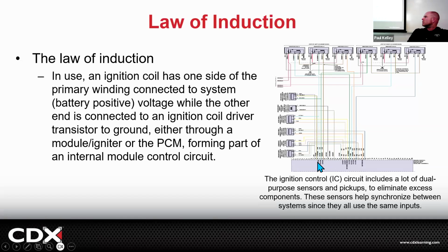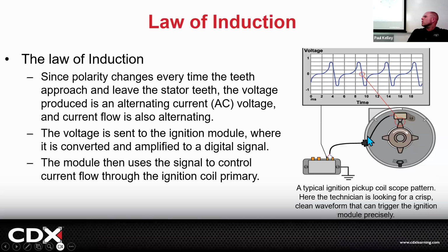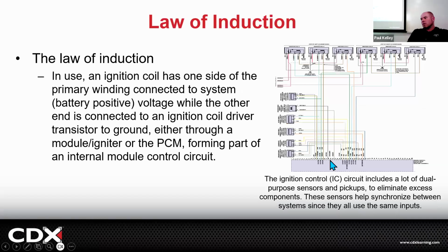Now we put the ignition control module in here, and we put a similar type of sensor, and it induces, and the ECM is like, oh yeah, I know where you're at. The tooth just passed, and we're waiting for the next tooth, right? So we're still using induction. That's kind of my point. This is old school, but we're still using induction on some that's computer controlled and fuel injection and everything.